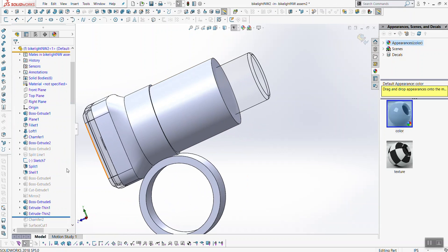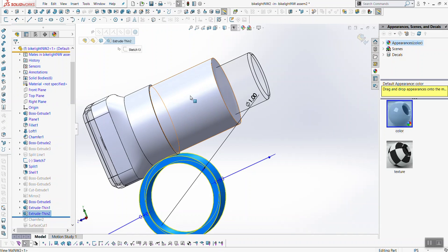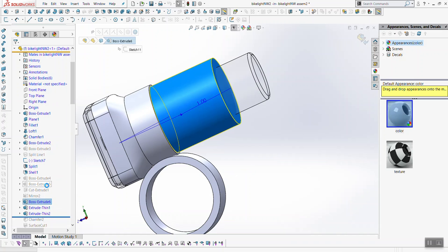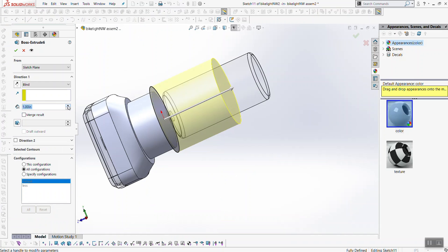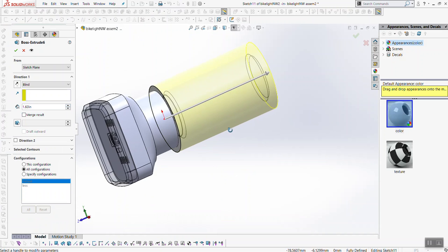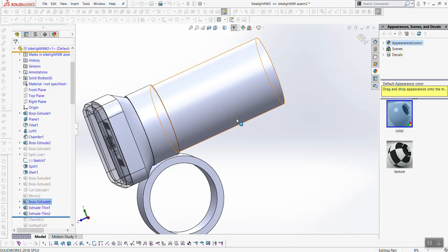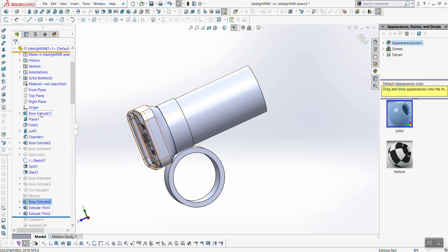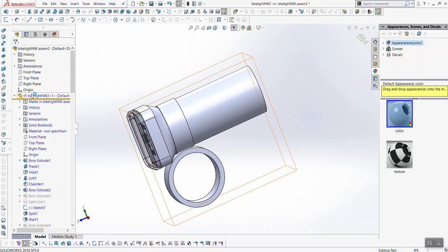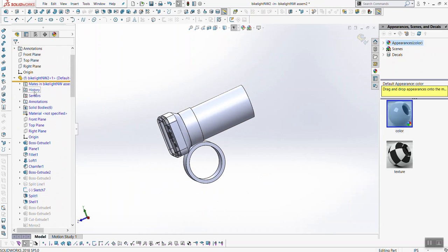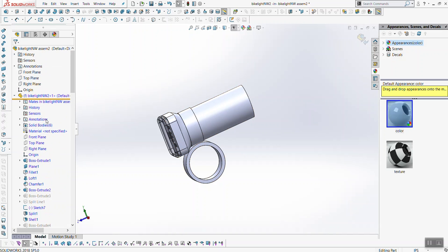You can see your guts in there. So for example, I can take this extrude command, edit it within the assembly, and then click on that till it's long enough to encapsulate the light back there, or sorry, the battery back there. Of course, if you're in this workflow, just please be sure that you are working within the part within the assembly. You don't want to be adding features into the assembly.